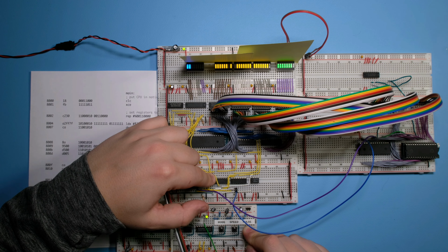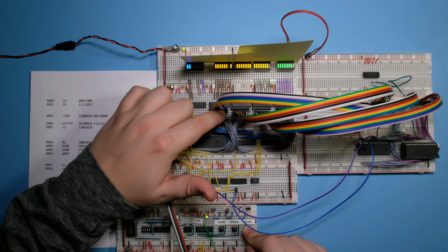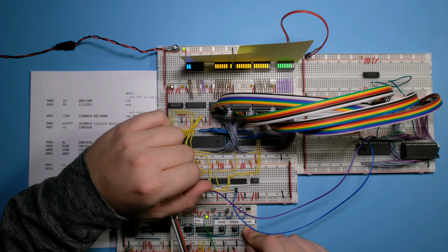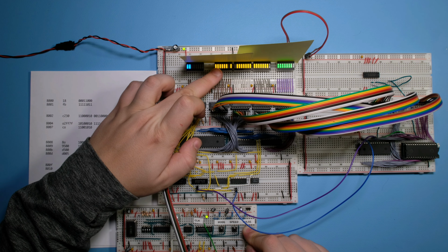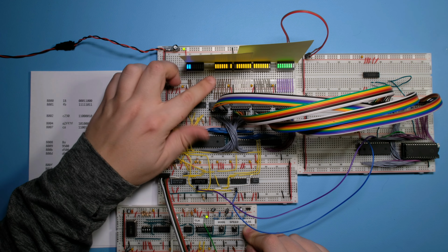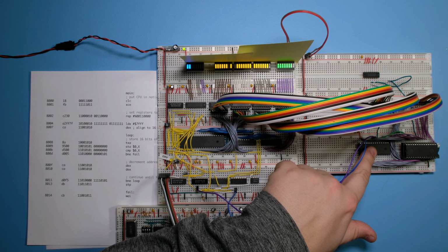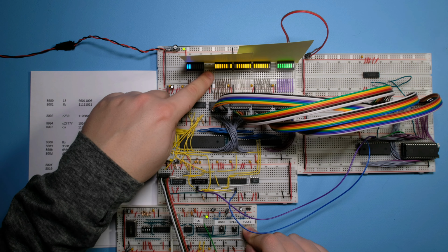And as we saw in the timing diagram of the CPU, the latching of the bank address is really sensitive to the speed of the chips. And so what I think is happening here is that potentially we are latching what's present on the data bus. So we'll have to fix that. But since we're ignoring the bank address in the RAM circuit, everything should still work fine.